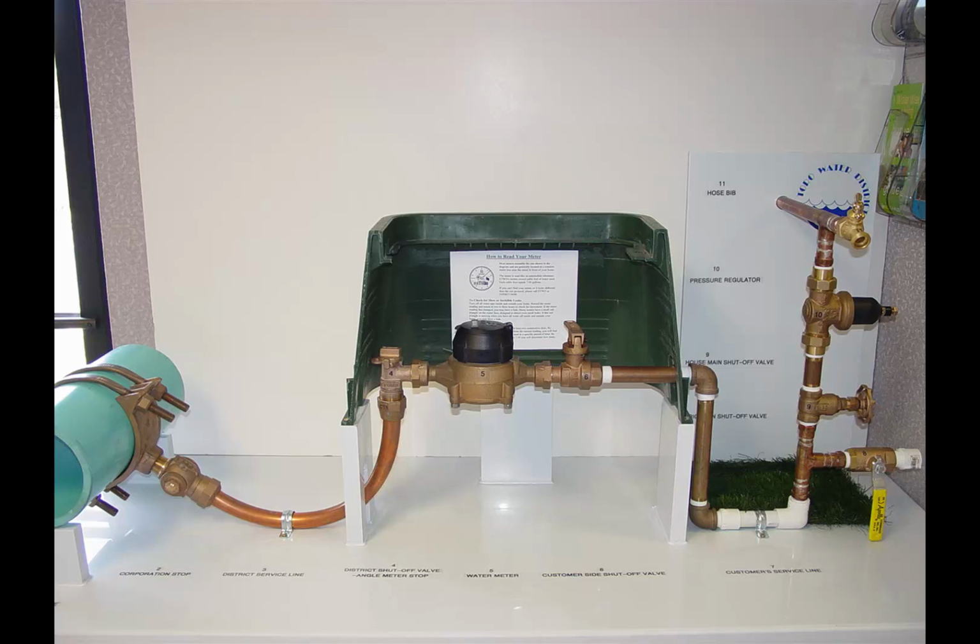So once again, you've seen this picture before, kind of bring it all back into perspective on our positive displacement meters and our billing meters. So we started with our saddle, we have our corporation stop, we have copper piping coming into an angle meter stop, in this case a compression by spin coupling. This meter has threads on both sides. I think it's probably a 5/8 inch meter. And then the customer side valve, which is just a little ball valve with again, spin coupling to connect to the threaded connection on the meter. And then it goes on to the customer side stuff.